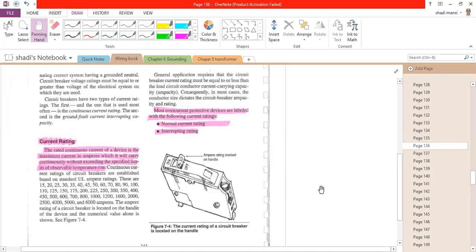You put 30 ampere, and all of a sudden after 5 years, 6 years, you added more equipment, for example, to the kitchen. Now you need like 45 ampere, but you did not change the circuit breaker. So what will happen to the circuit breaker? Basically, the circuit breaker will start tripping all the time. Tripping means it disconnects. Why does it trip? Because now we have the overload condition. Once you run all the appliances together, let's assume you will draw like 37 ampere, then the circuit breaker trips because we have overload condition. This happens when you start adding more appliances in the kitchen, for example, without considering the fact that the circuit breaker is not changed, okay? This is very important.